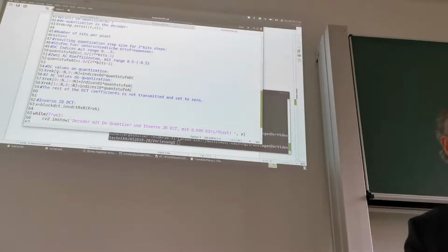Make sense? So this is the purpose here of this upsampling of the indices, that the AC comes at the upper left-hand corner on each block, on each 8 by 8 pixel block. And correspondingly from the DC coefficients, starting at position 0, 1 in the upper left-hand corner, so that's the one next to the DC, and then repeating in every block of 8 by 8 pixels. Again here, every 8th sample is assigned.